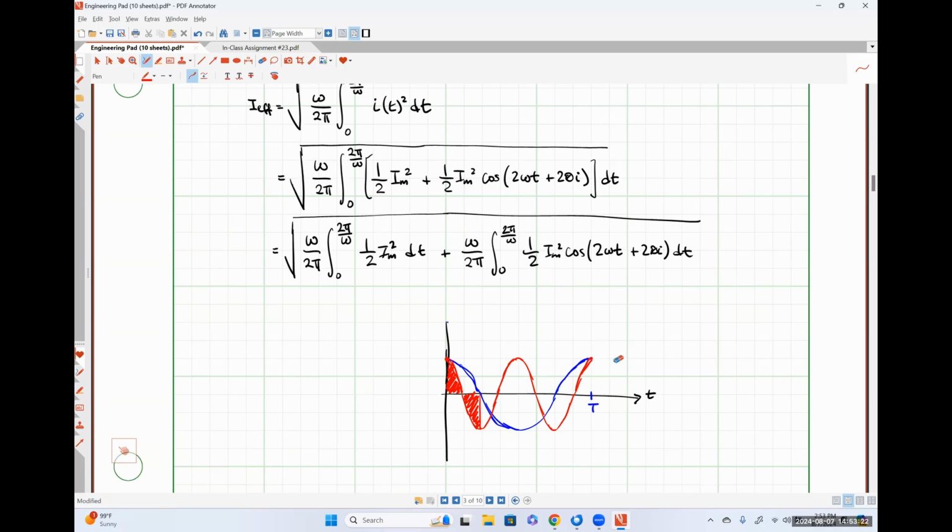So all we're doing effectively with our integral here is we are integrating this sinusoidal signal over exactly 2 periods of the double frequency signal, okay? Anytime that we integrate a sinusoid over an integer number of periods, the answer will always, always, always be 0.